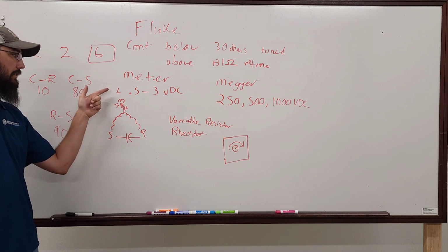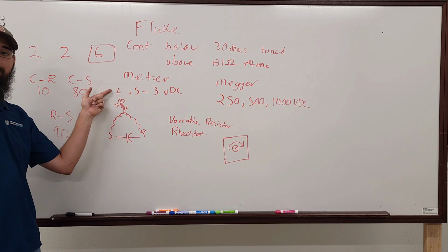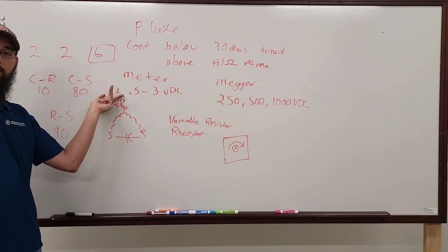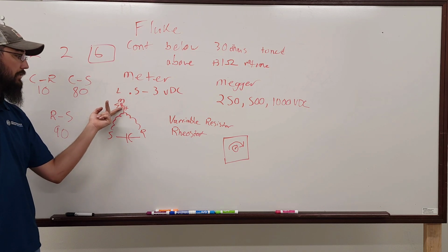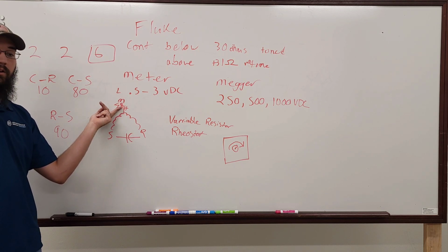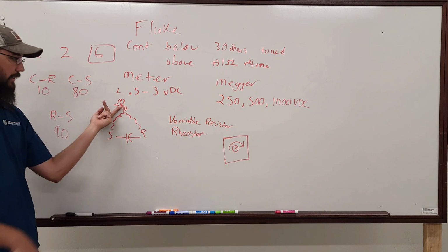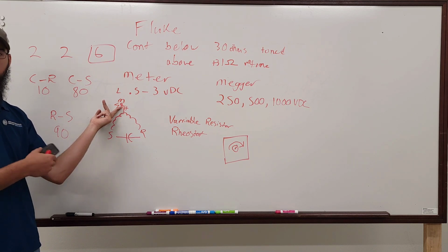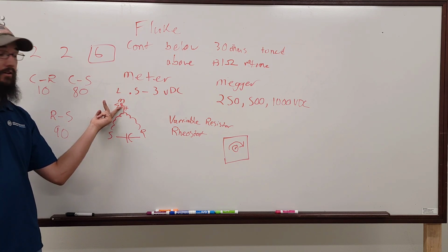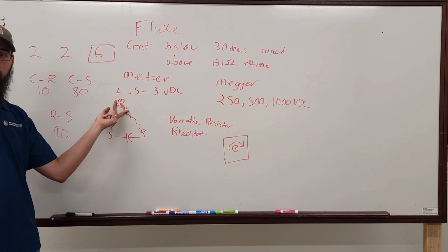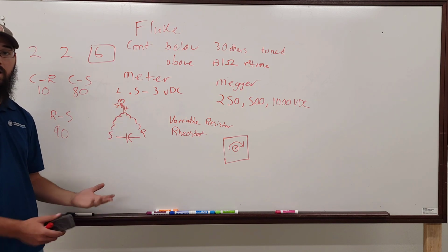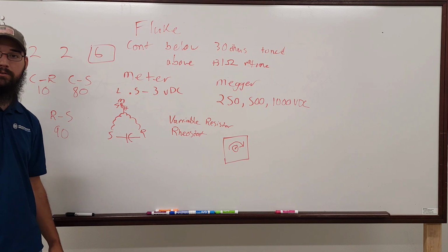actually it was the heat. The heat was running on the low speed tap. Well, the point of the coil right here between the low and medium speed, actually no, it wasn't even that. It was between the medium and high, this exact scenario. It was a residential service call way back in the day. It's severed right here. The resistor, the winding, whatever was there broke right here. But the high was still connected. Well, that's all I had to do. I just moved the wires to another tap. Instead of being on low speed, I moved it over to high. It got them functional until we could get the proper motor.